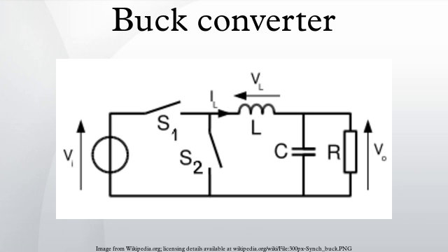In addition, power loss occurs as a result of leakage currents. This power loss is simply ILEAKAGE times V, where ILEAKAGE is the leakage current of the switch, and V is the voltage across the switch. Dynamic power losses are due to the switching behavior of the selected pass devices. These losses include turn-on and turn-off switching losses and switch transition losses. Switch turn-on and turn-off losses are easily lumped together, where V is the voltage across the switch while the switch is off, TRISE and TFALL are the switch rise and fall times, and T is the switching period.